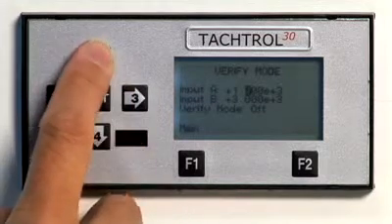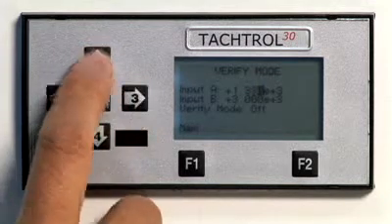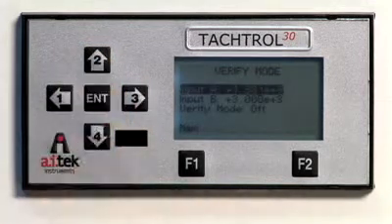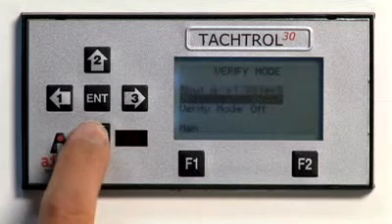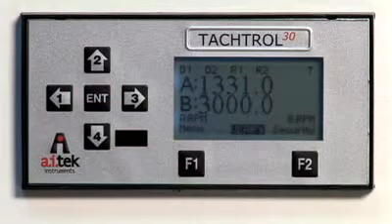Press Enter to view the available user-defined constants. Verify allows the user to configure set points and outputs, then apply a simulation of the expected speeds or counts to the instrument to see how each will react. When changes are complete, press F1 Main to exit to the main screen.